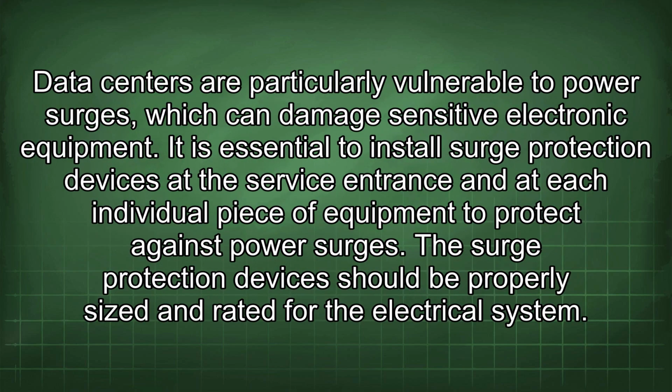Data centers are particularly vulnerable to power surges, which can damage sensitive electronic equipment. It is essential to install surge protection devices at the service entrance and at each individual piece of equipment to protect against power surges. The surge protection devices should be properly sized and rated for the electrical system.